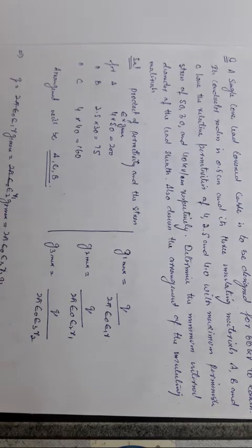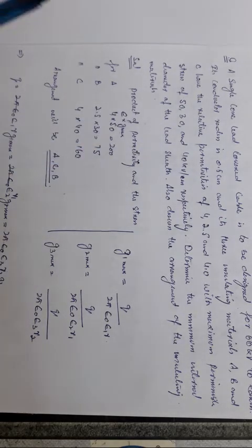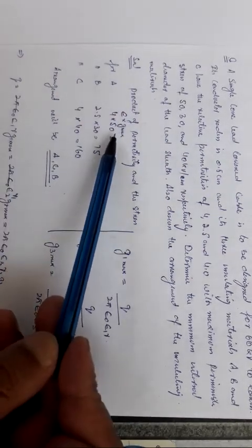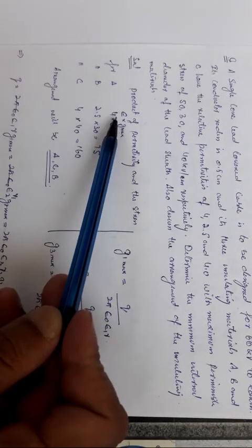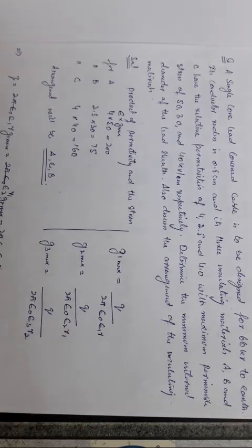So we know that in the first case, the dielectric material whose permittivity is maximum, we use close to the conductor, and then the other ones as per the descending order of their permittivities. In the previous case it was given that G max is same, but in this case G max is different. If G max is same, you will see the same pattern, that whoever has the highest permittivity has to be kept close to the conductor. But in this case, since the G max are different, we have to take the product of the two.